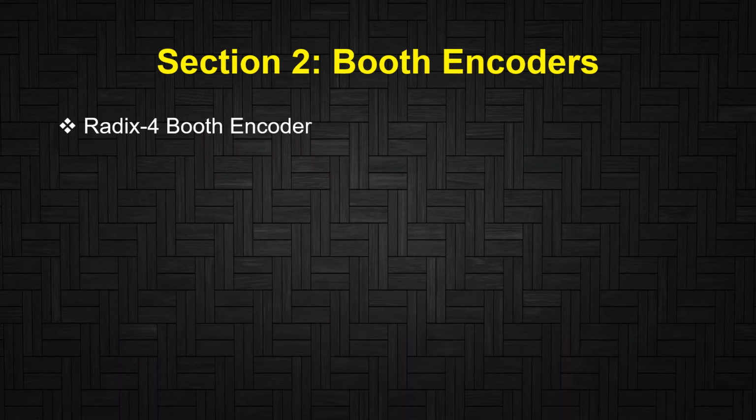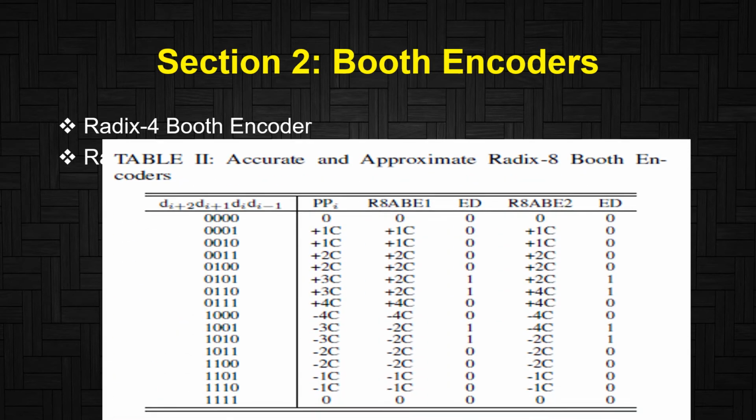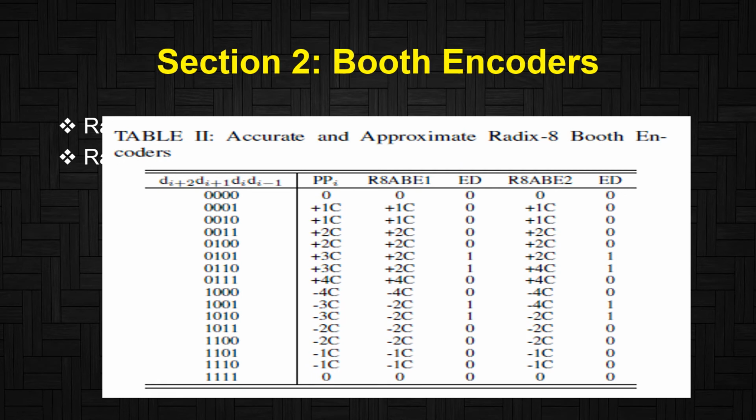After that, we discuss the radix-8 Booth encoder. In the radix-8 encoder, the input D is grouped using overlapping 4 bits. Sign, 1, and 2 signals are used for the same objective as in radix 4, whereas 3 signifies the need of the odd multiplicand 3C and 4 specifies the 4C partial product. Higher radix encoding reduces the number of partial products significantly, so the partial product accumulation can be pursued by simple tree architectures.